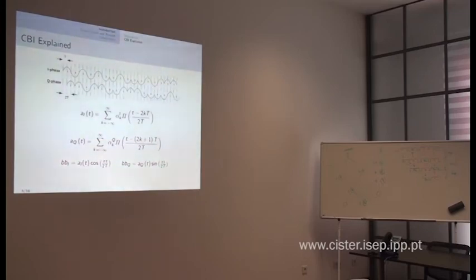You're going to do these tricks that I'm showing there with some mathematics, shifting by 90 degrees in phase, and you're going to transmit these two streams of bits at the same time. The reason you can do that is because you will use synchronous demodulation, which gives you two independent components, linearly independent, that you can recover in the receiver. That's what this cosine and this sine do. The out of phase component allows you to transmit twice the information. Instead of one wireless channel, you have two.